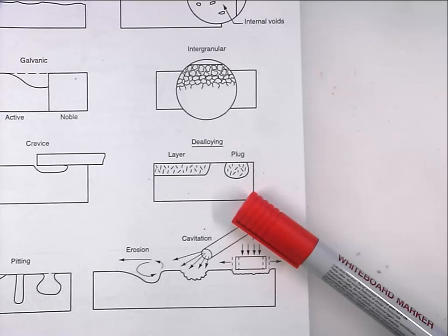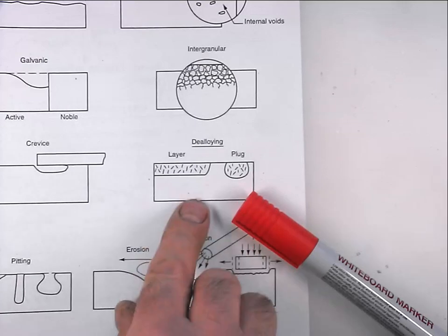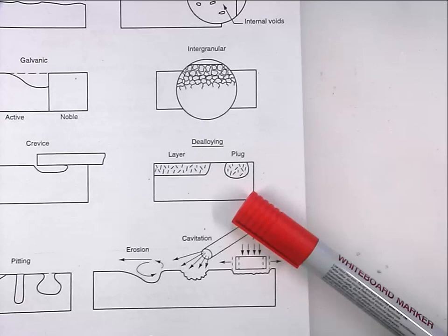If you take a slice through it, you can see that it's brass coloured in the centre, and if you look carefully round the edge, you'll see that it's discoloured. It's beginning to get less golden coloured around the edge, that's where the solution has been starting to attack the zinc and dealloy it, to leach it out of the component. And obviously that reduces the mechanical strength of the component and can lead to failure. So galvanic corrosion can cause failures.